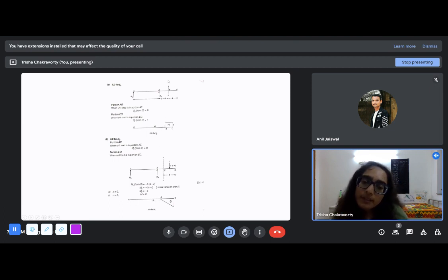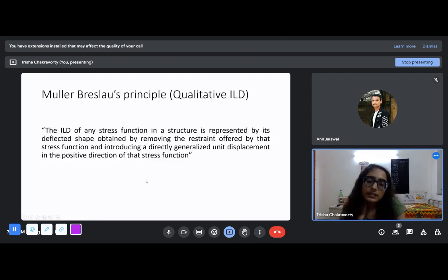And from here, when the load is here, if you come from the right side, like if you take the shear force at E, you will get it as +1 because though the load is downwards, when we come from the right side, downward shear is positive. And for the moment as well, you can see if there's a 1 kilonewton applied here at a distance x, this will be 1 into b minus x. So this is how this will look like.